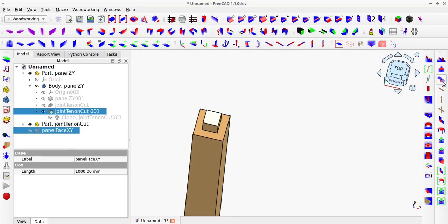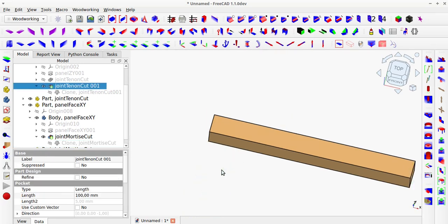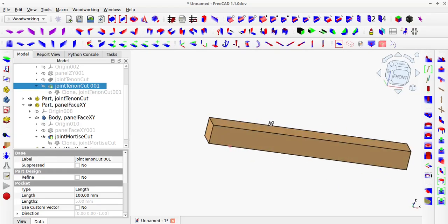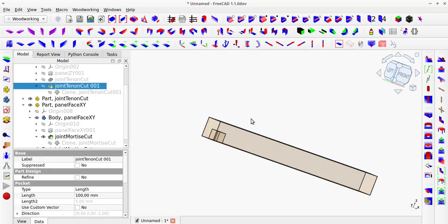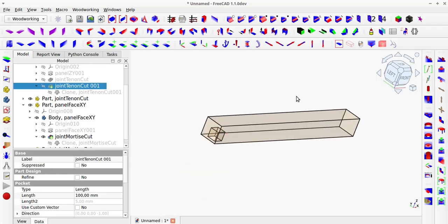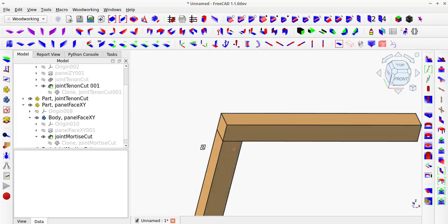be cut. You can see in the element tree on the left that all the necessary elements are selected, even if the element is not visible, and then simply use the Joint Mortise Cut tool. After the mortise is cut correctly, the element will reappear automatically. Thanks to this complex selection, you can control the mortise cutting process and decide which tenons to skip during cutting.